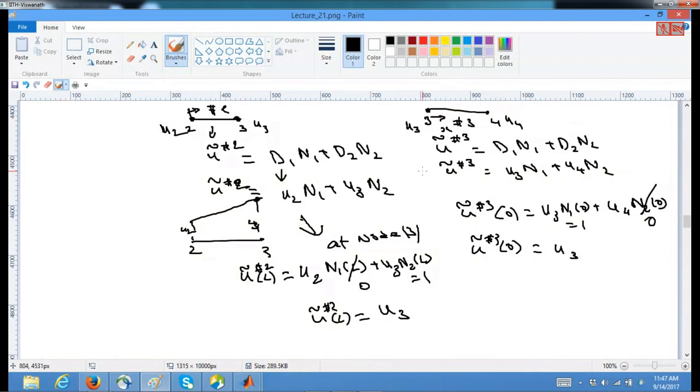Because at nodes the finite element has to exactly agree, and this element and that element have a common boundary which is nothing but node 3. The boundary between node 3 is the boundary between element 2 and element 3. So the node itself is the boundary, but at the node this is exactly obtained no matter whether you are coming from this polynomial or from that polynomial.